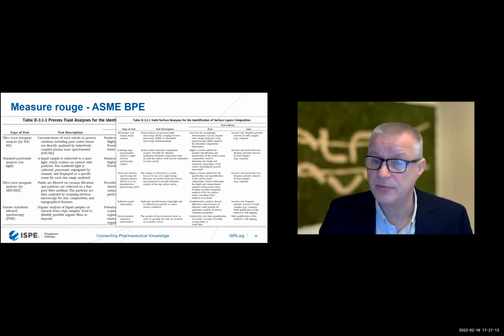But at the same time, we can say the more ozone you have in the system, the easier it should be to create the passivating layer. But it's a mix there. What does it generate first? And it has been seen that ozone will increase rouge formation slightly, not a huge amount, similar to temperature, in the same way as the temperature does.